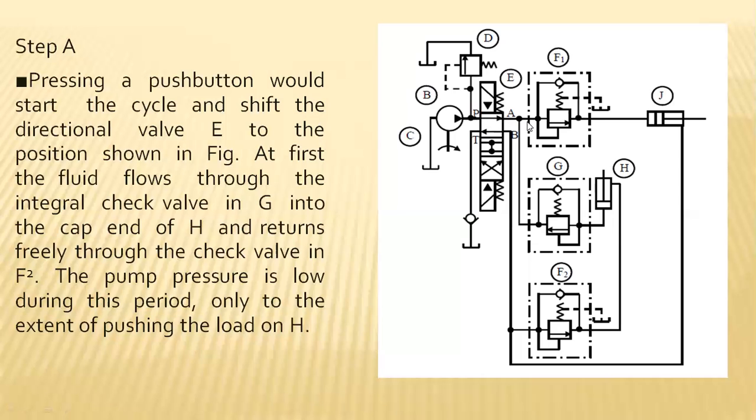Forward motion. With this forward motion, one sequence valve is arranged here, and the outlet of this sequence valve enters the inlet of J, that is the first actuator. Commonly, a junction point exists here, point A, which splits again in the forward direction along that channel line to pass the motion to the second actuator also.